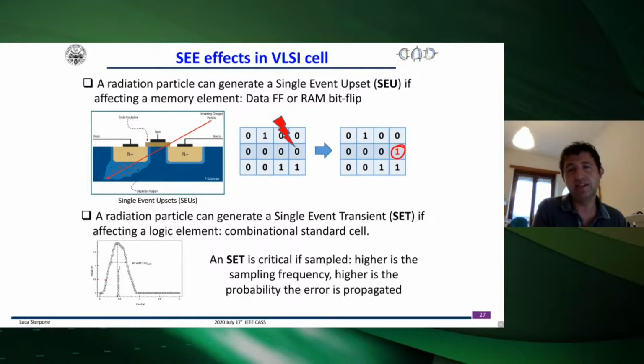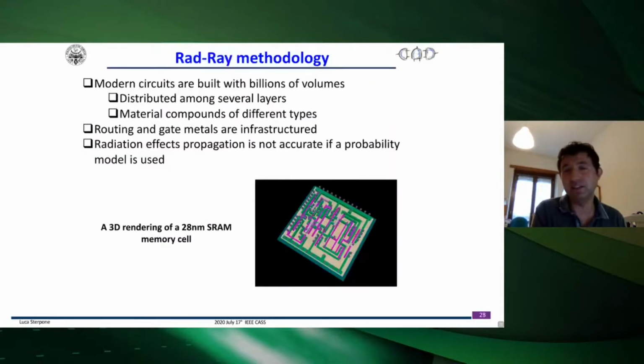Here there is a transient phenomenon, which is, as you can see, a change of the voltage status. Here I suppose I have my signal at 0, and then suddenly my signal jumps to 1. These two phenomena can happen in different positions in our technologies. To identify where this technology is sensitive to this radiation effect, and later to identify where on the FPGA we have this effect, we need some methodology.